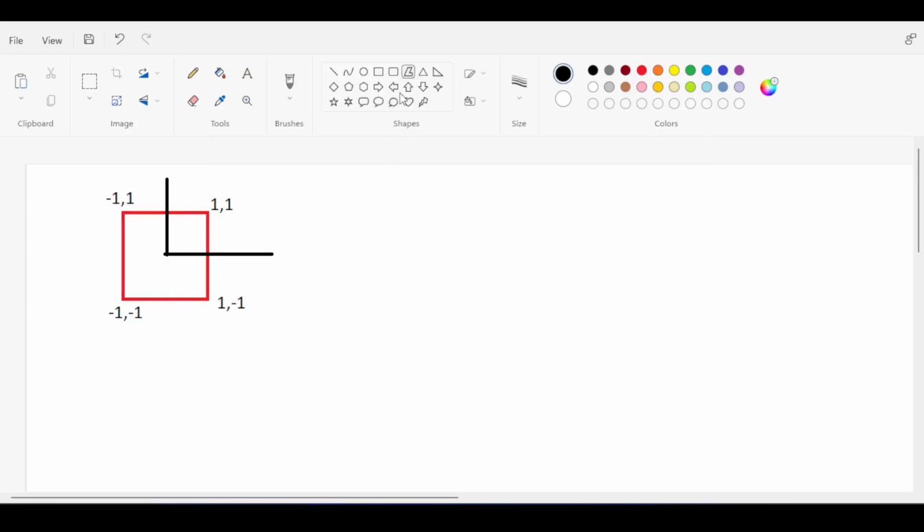Now, your elements in the finite element mesh are not going to be rectangles. If they are rectangles, then they are perfect. But if they are not rectangles, for example, if you have some strange element like this, which will happen, then this is not a rectangle and needs to be mapped into the isoparametric element. Now, what does mapping mean?